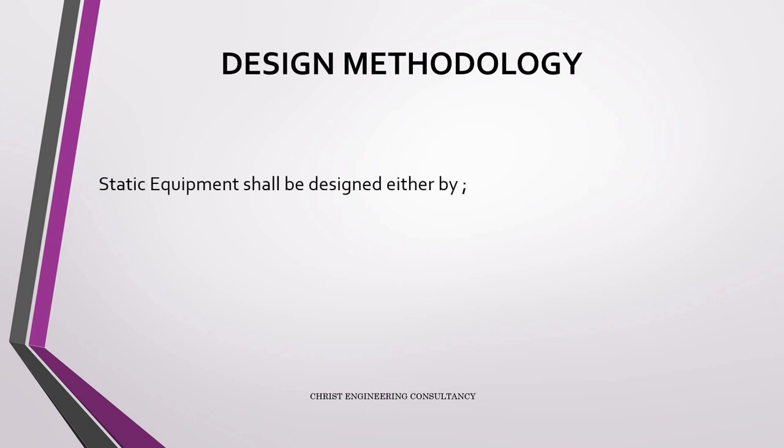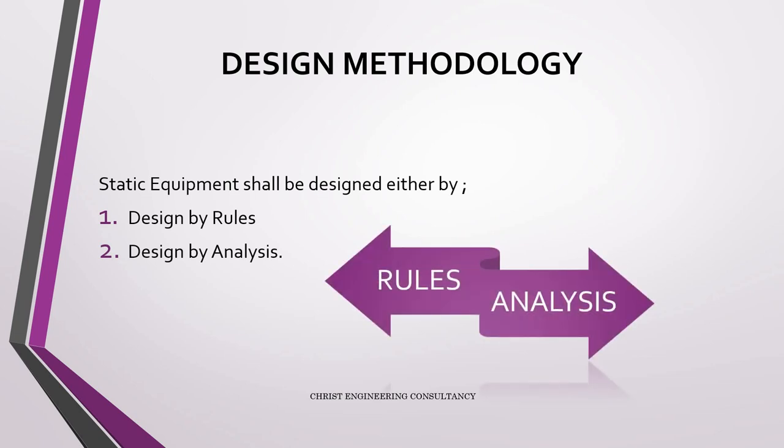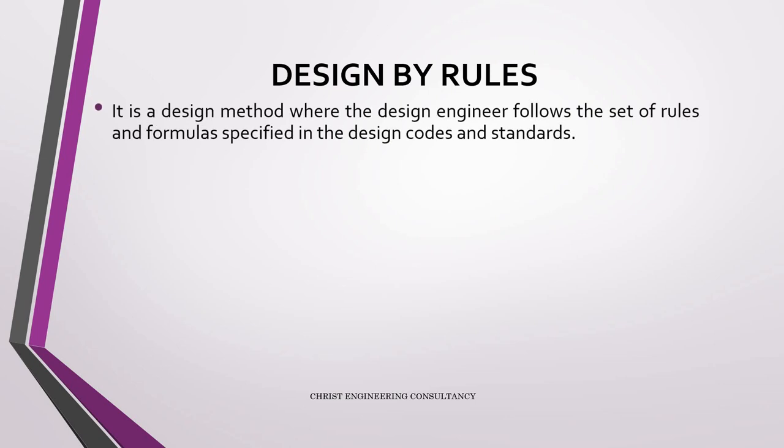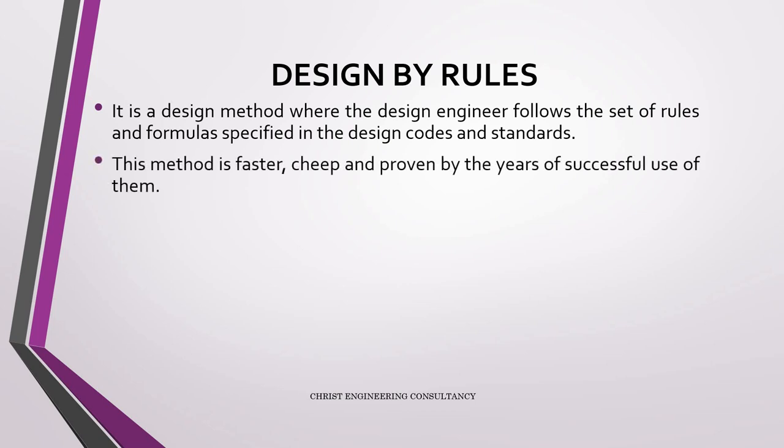Design methodology. Static equipment shall be designed either by design by rules or design by analysis. Design by rules. It is the design method where the design engineer follows the set of rules and formulas specified in design codes and standards. This method is faster, cheaper and proven by years of successful use of them.